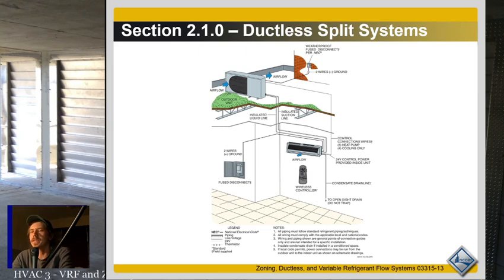Remember, when you're talking a ducted system, you can have 25, 30%, sometimes even more losses just in the duct. So if you've got ducts in an attic, then 25% or more of the heat or cooling you create, the heat you produce or the heat you remove, is going to be lost just in the ductwork. So that system that's in that air handler in the attic connected to ducts in the attic, if that's a 2-ton system, the load for the space is probably only about 1.5 tons. A half of that ton is lost in the ductwork. So that's a pretty large system loss, right?